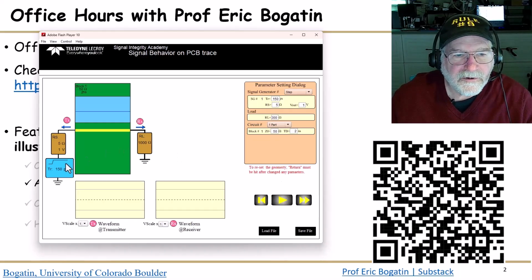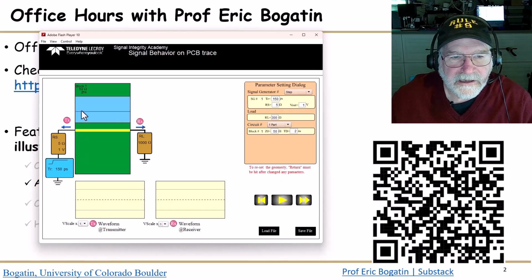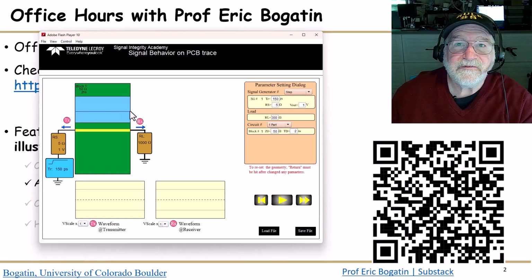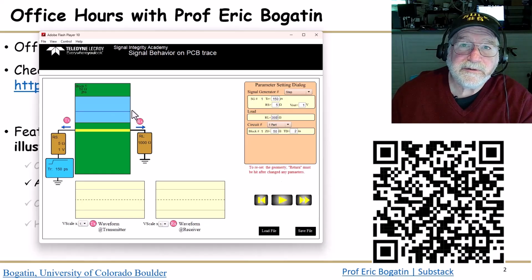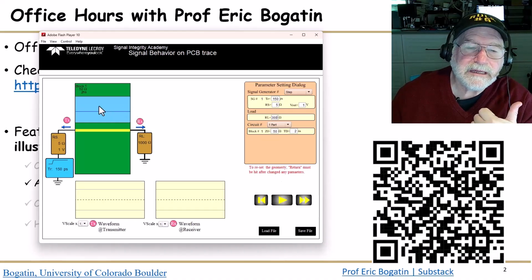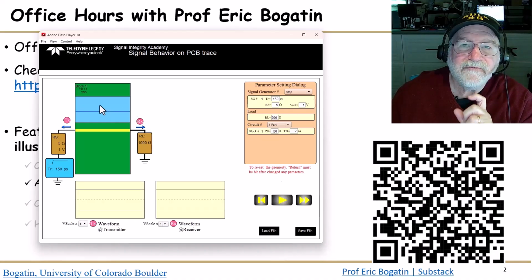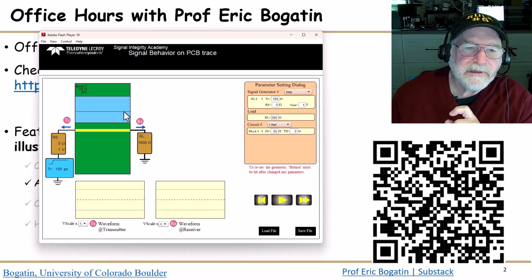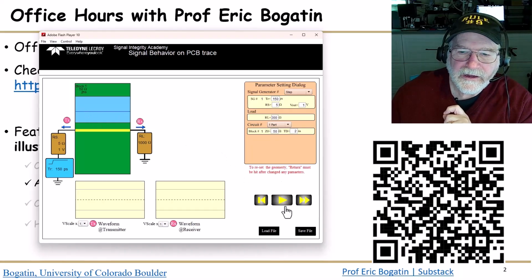So before we start, we're going to see that signal launch down the line. It's going to propagate uniformly. When it hits the end, it's going to reflect, and the reflection is going to be 1, so whatever goes in, we're going to see coming out. And we want to look at the voltage that we would see at the end here from the two waves, plus that instantaneous voltage. So let's run it, and I'm going to stop it partway through here.